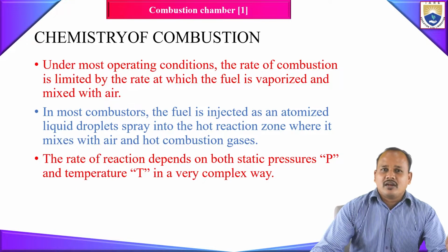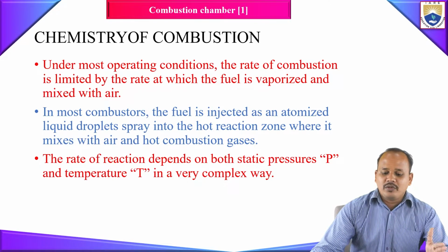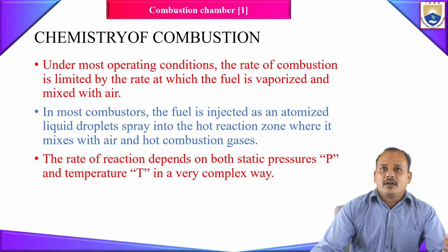If you are not going to inject your fuel in fine droplet form, what will happen? It will take more time for the fuel droplets to evaporate. So obviously, the mixing won't be thorough. In order to do the thorough mixing, you have to inject your fuel in droplet form.